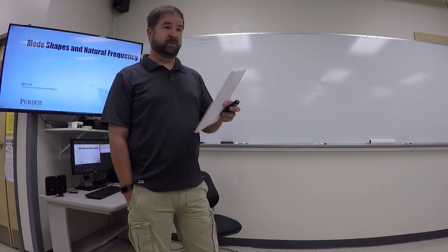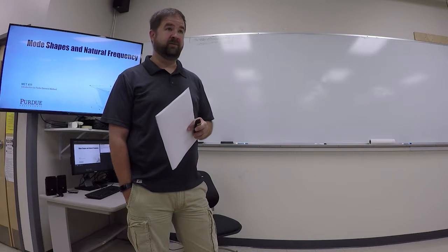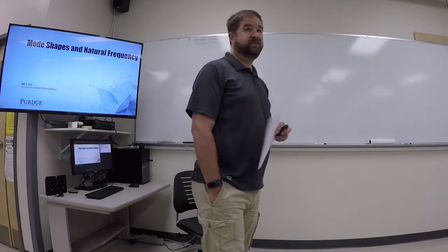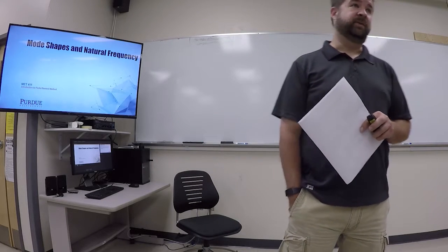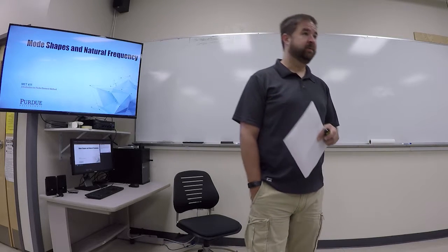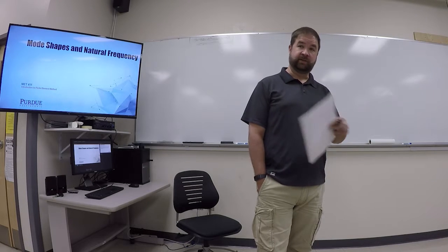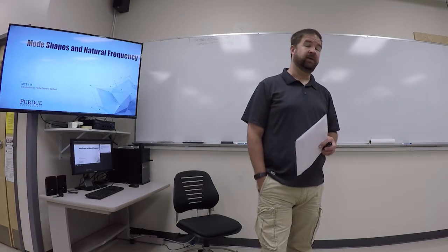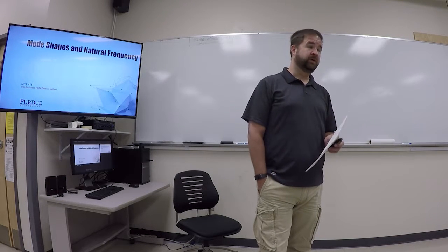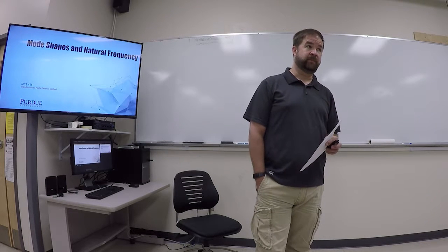In our analysis, we need to tell SolidWorks to calculate the first 11 so that we have 5 non-zero ones. Obviously, as you do the analysis, if you just ask for the first 5, it will tell you all zeros, and you can say, well, they're all 0, so now give me the next 5. And then if you have a few zeros in there, you can keep increasing your increment too. But if you just tell me modes 1 through 11, then we'll get 5 non-zero ones that we'll report.